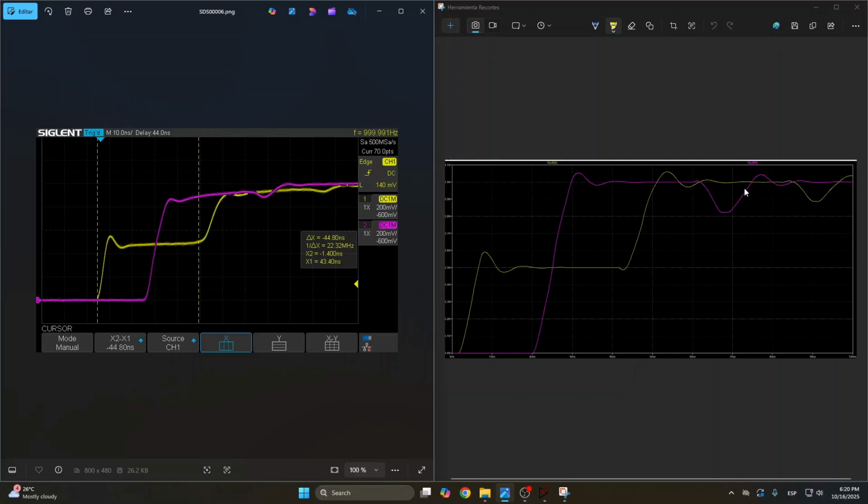And in a complex board with other components, with a lot of traces nearby, you are going to observe a lot more of this kind of ringing and noise. If you don't pay attention to those reflections, you can have false triggers in your logic inputs or your receivers. Or if these overshoots are too large, you can exceed the voltage tolerances, or the maximum allowed voltage of certain components, and that could produce damage or strange behaviors in some cases.